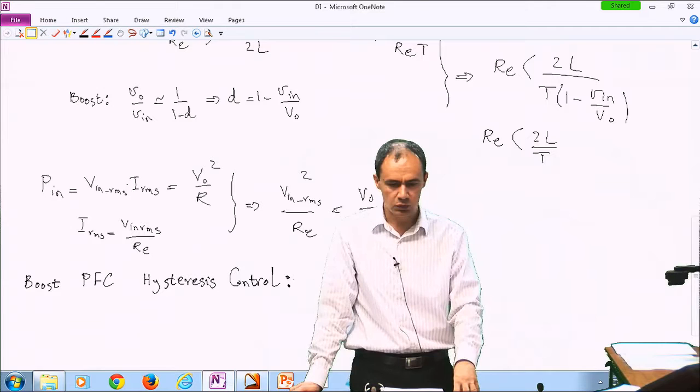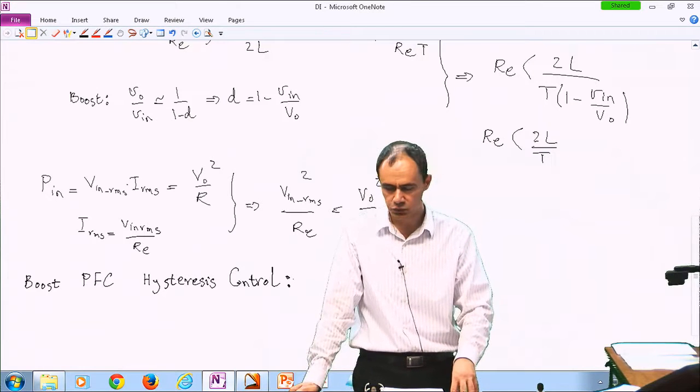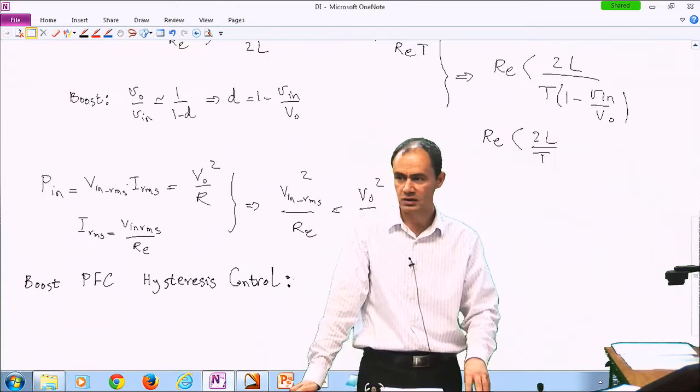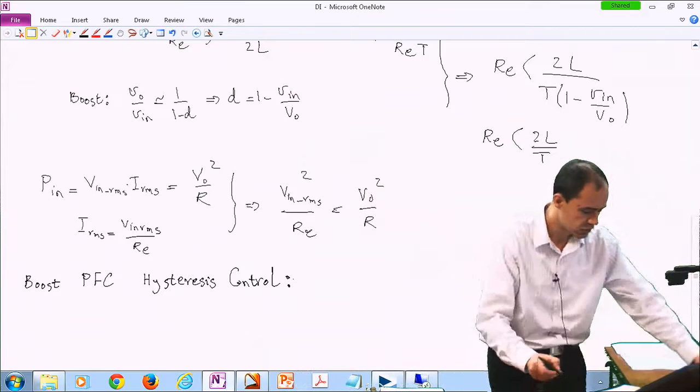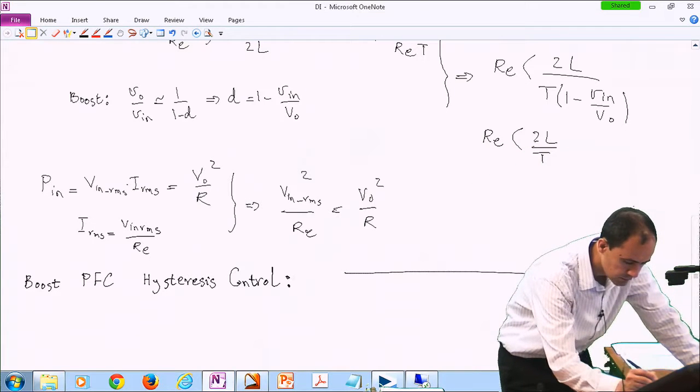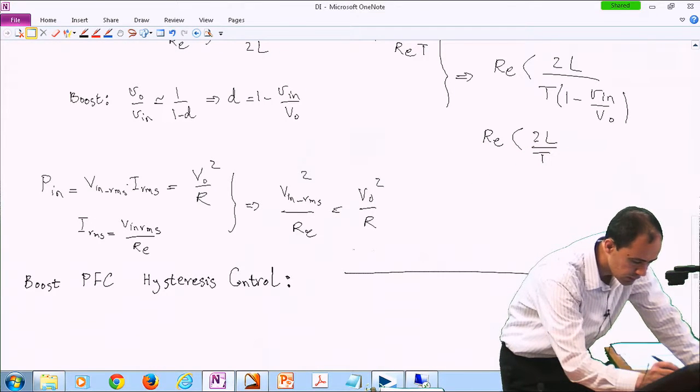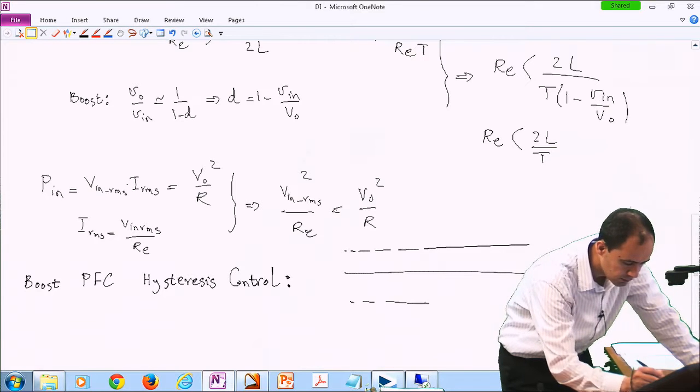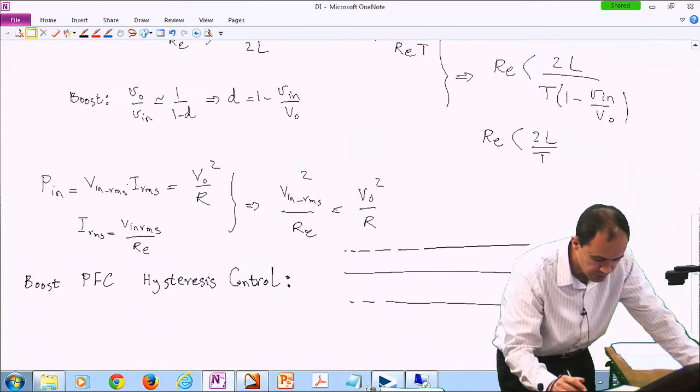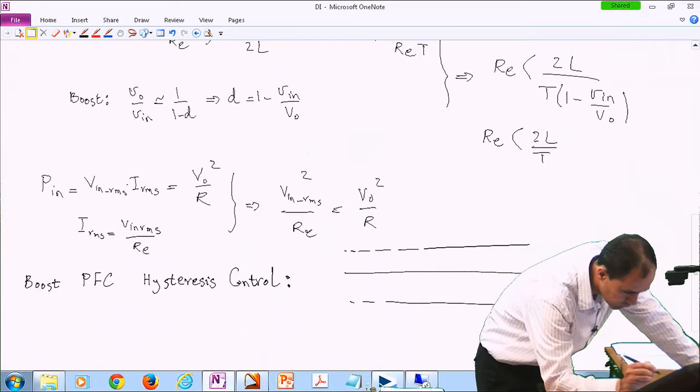And if the temperature goes below 72 degrees minus 1, you turn the air conditioner off. So this is your set point, 72 degrees. Then you have a band. The thermostat actually has this band. You don't adjust the band. So let's say the band is 1 degree.